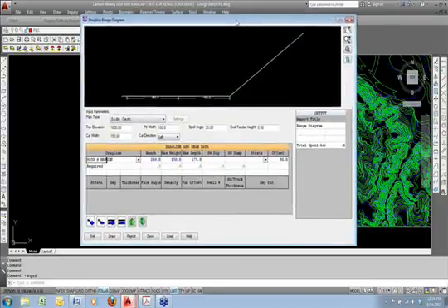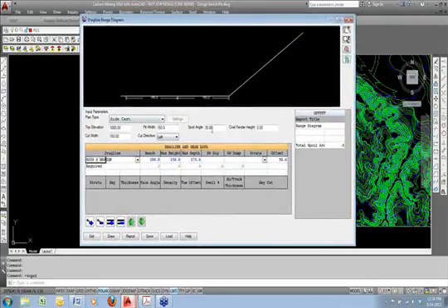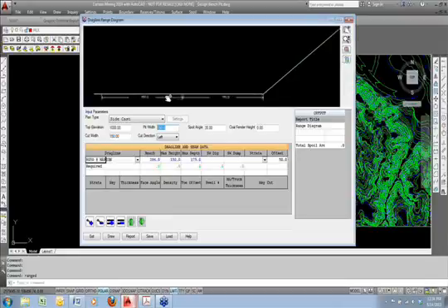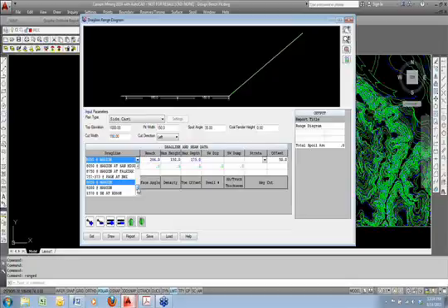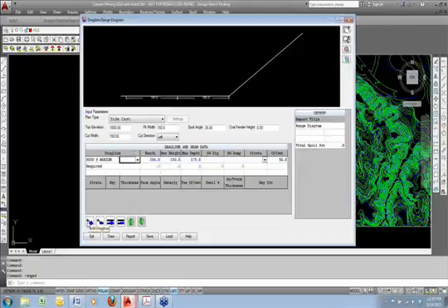So if you haven't seen this command at all in 2013, I'll go ahead and start from the beginning. You set up your initial cut and pit width. So that would be this is the open existing pit, and this is the future cut, 150. Everything's labeled up in the preview. You set up your initial spoil angle in degrees, and you choose your drag line down below. There's a list of about 40 drag lines included with the program. These are the same that are used with the cut in place, and you can also add your own to this list. And then you start by adding the different seams and drag lines down below.